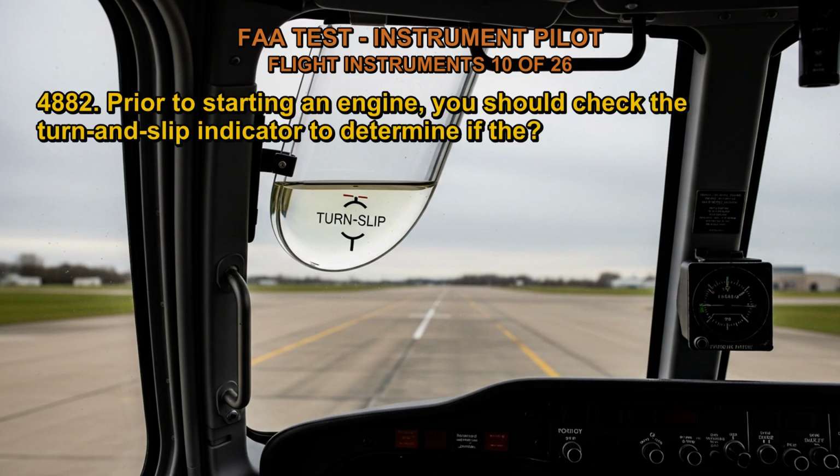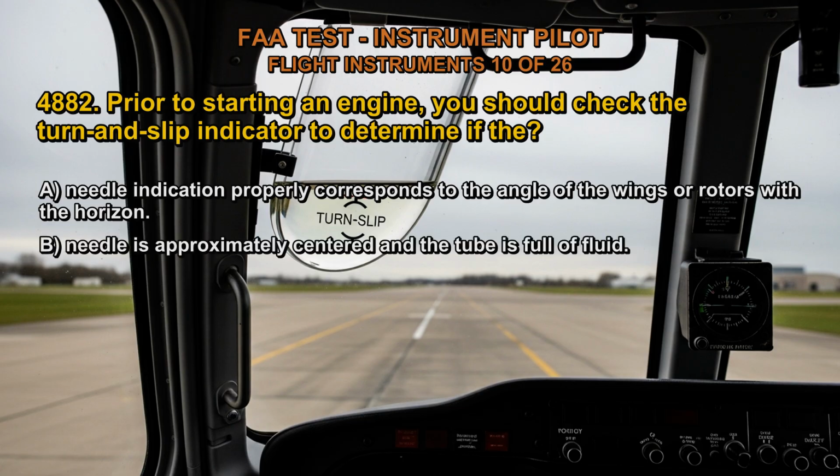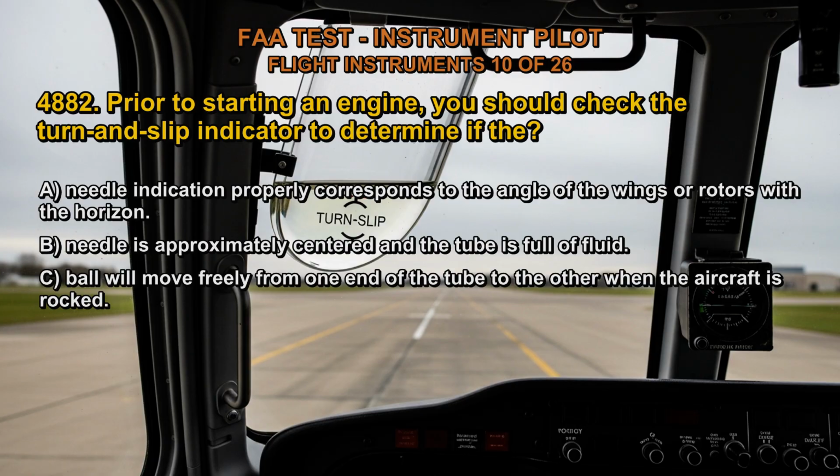4882. Prior to starting an engine, you should check the turn and slip indicator to determine if the A. Needle indication properly corresponds to the angle of the wings or rotors with the horizon. B. Needle is approximately centered and the tube is full of fluid. C. Ball will move freely from one end of the tube to the other when the aircraft is rocked.